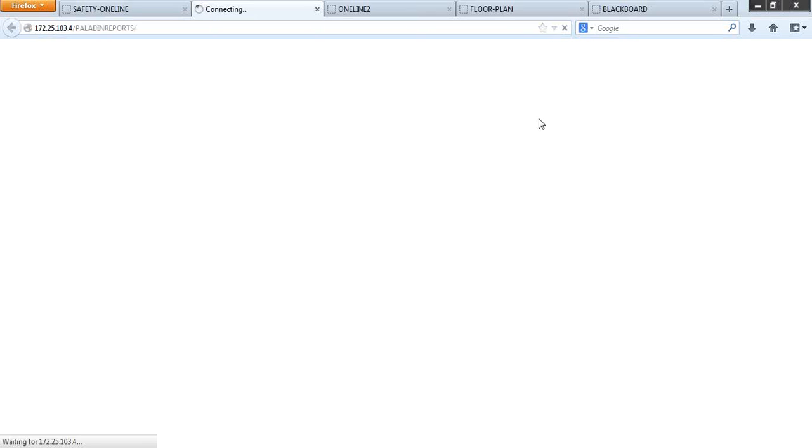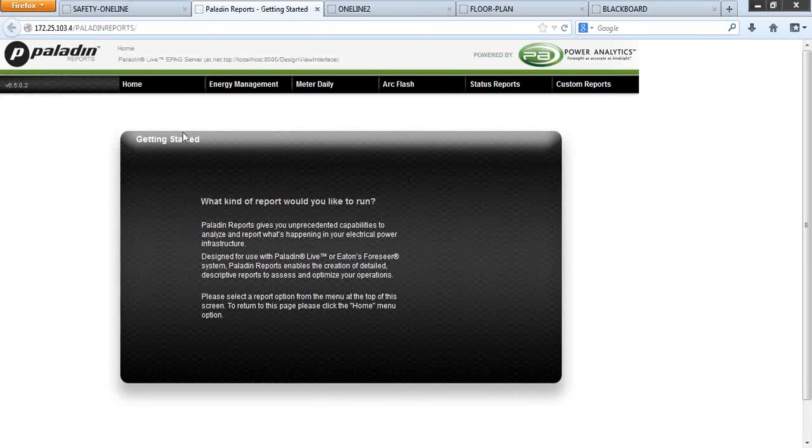And then, of course, we go to our Paladin reports, which also allows you to not only do an arc flash report, but it gives us our meter daily reports, energy management, some status reports, custom reports. From here we could plot our SCR reports giving us our timestamps and status of our breakers.